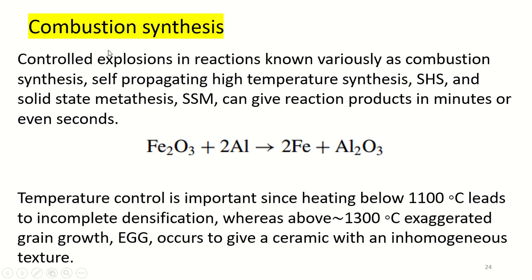The resulting material is a fine powder, since gas evolution during the reaction prevents agglomeration. Agglomeration is the process in which some of the particles combine together and form big chunks. So it will reduce the agglomeration process. The powder may then be pressed into pellets and heated at high temperatures to give dense ceramics.